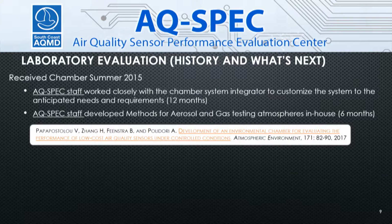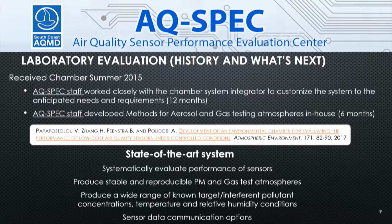Results can be found in an article written in Atmospheric Environment on the development of an environmental chamber for evaluating the performance of low-cost sensors. So the result of that is we have a state-of-the-art system. It's able to systematically evaluate the performance of sensors, able to produce stable and reproducible aerosol and gas test environments, and also do that across a range of relative humidity, temperature, and target pollutant and interferent pollutant. So if we're testing ozone sensors, we can also test that sensor for interfering pollutants. The system is also set up for several different data communication options for sensors.